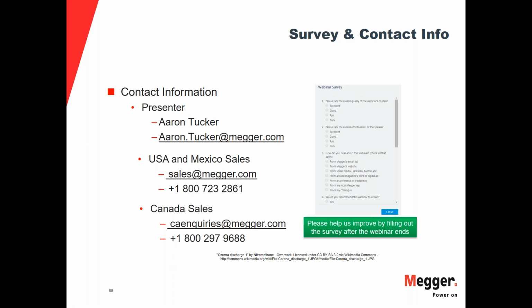Okay, I'll take that question. Interesting to ask about the frequency of testing, right? You may not have time to test your transformer. You may not have the opening, or operations will not allow you to do the testing on the frequency that you may plan to do it. But the only reference that I can suggest you to look at is the NETA MTS, which is the maintenance testing specification. And if you look into this document, there's Annex B, where it will show you the frequency, at least the recommended frequencies for testing any piece of equipment.